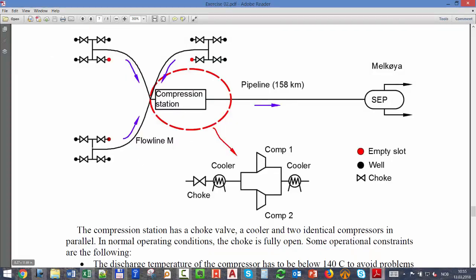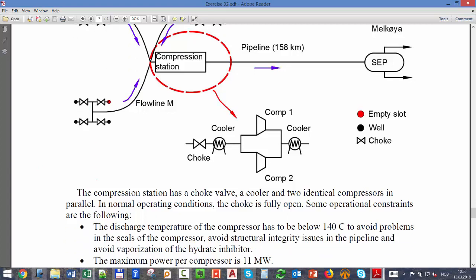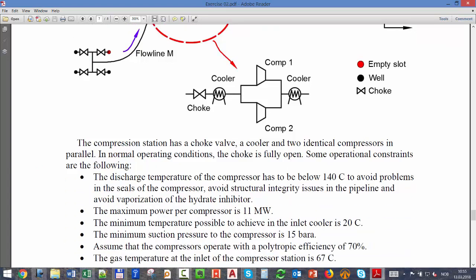Temperature, okay? Remember, here we are designing so far to bypass this guy. But actually we have this cooler here that we can use to bring that point inside. So remember that cooler I told you in the case of Oscar can go all the way down to 20. And here is also the same, so I use the same number. Here the minimum temperature we can reach will be 20. So let's see how temperature affects that.